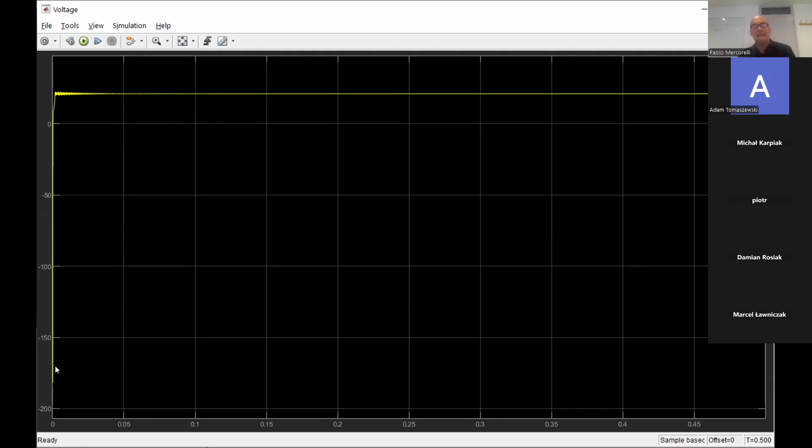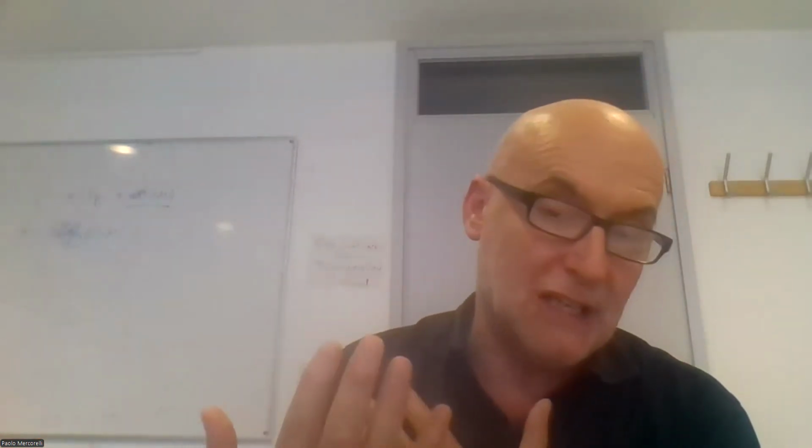But it's not important, the amplitude. Of course, it's important because if I exceed the threshold, it could be dangerous for the system. But more important is the energy of the input. You remember, the sum of the U square. This means I have to sum over the time the square of this input here. If you want, you can do it all. But anyway, this is the idea that we can realize intuitively: decreasing Q and increasing R, I will have a larger error, but less energy in input.